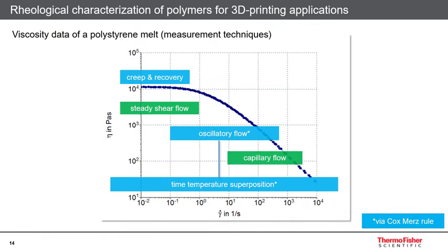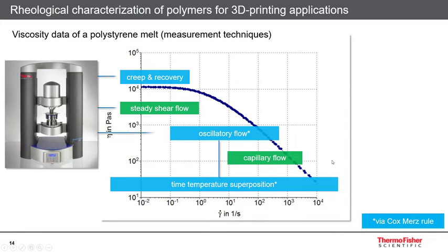This slide illustrates different measurement techniques for viscosities in the different shear rate ranges. In order to create a complete viscosity curve that covers all three ranges we have discussed on the previous slide, different measuring techniques are available for the different shear rate ranges. Standard shearing tests with rotational rheometers do usually only give access to the zero shear viscosity range. For viscosity data at higher shear rates, traditionally measurement techniques that utilize capillary flow are performed. These techniques include measurements with instruments like a classical melt flow indexer, but also channel flow tests with specific dies in an extruder setup.